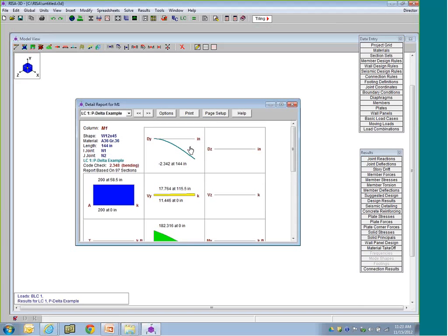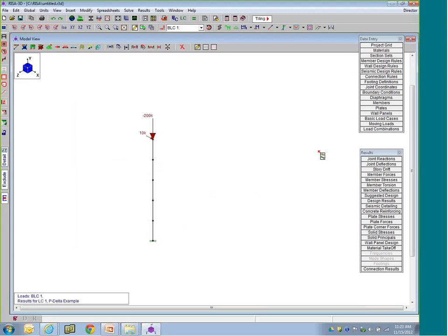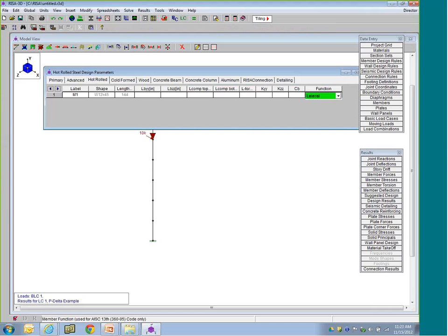The adjust stiffness method really kind of replaces the K factor that used to be in the older codes. The K factor was kind of just a fudge factor that was applied to adjust for these types of stability issues. And so now the K factor is always really going to remain at 1.0, which is our default. So we leave this blank, and the K factor is 1.0. And then if you're using the direct analysis method with the adjust stiffness on, that will take care of the factors that you were trying to account for in this K factor.